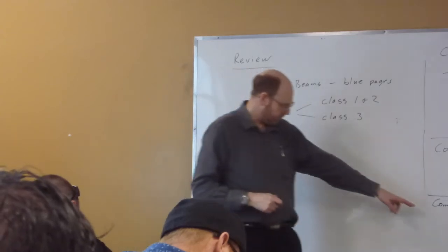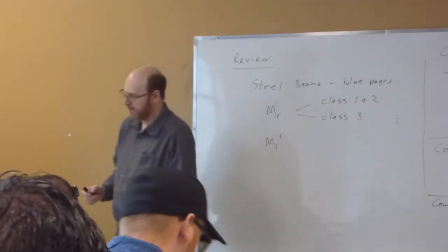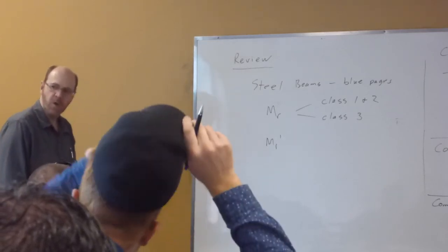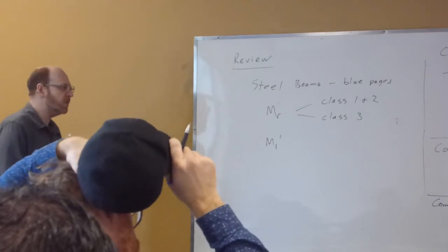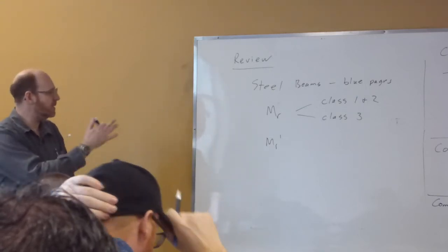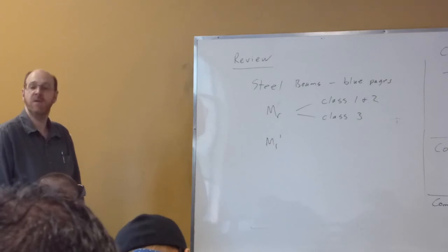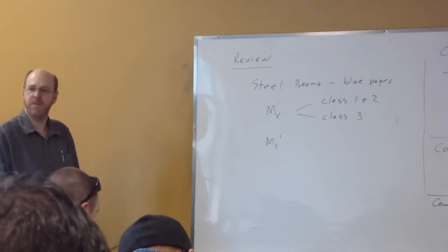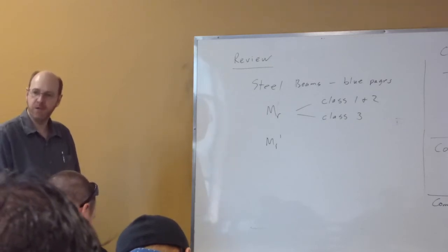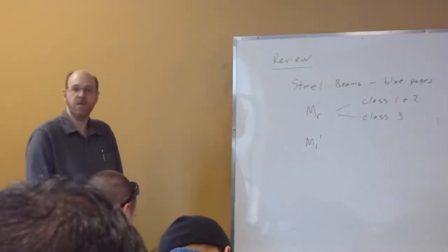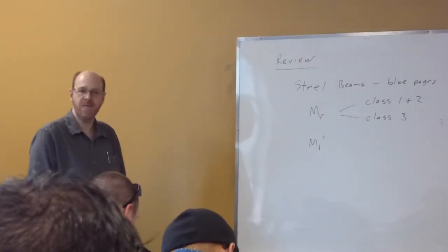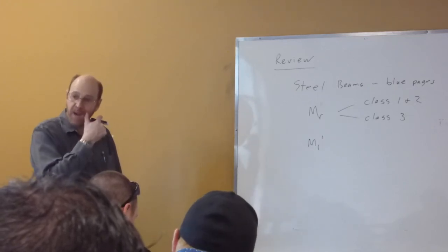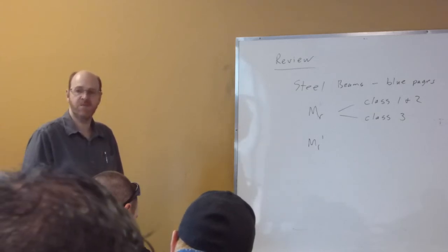Now with our composite deck, the reason we talk about composite deck in here is because this is the one real case that we looked at where we actually take into account construction loads separately than service loads. Right? So pretty much everything that we've looked at, the wood design and most of what we looked at in steel and even in concrete as well, what we're focusing on is we have this design value that we want to be able to match or meet. And it's based on how much load we expect on the structure when the structure is in use. Now here with our composite deck system, we're looking at different loading patterns for different phases of construction.